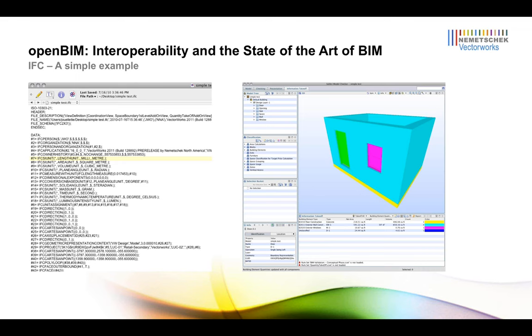Now, it's a little bit cryptic, but you can go through and it has line numbers, and there's a nomenclature there that is understood by the human being. So the information of IFC is not only machine readable, but it's also human readable. And this information can be viewed and analyzed by other IFC compatible apps for purposes like quantity takeoff or model information verification. One of the tools that we use, at least internally a lot, is the Solibri Model Checker. And especially with version 6.1, they've added this new information takeoff capability, and it's a pretty powerful tool.